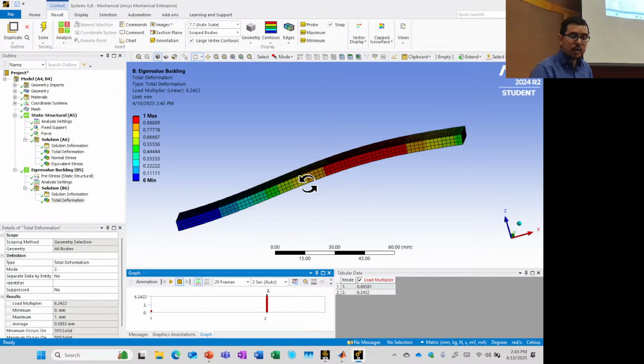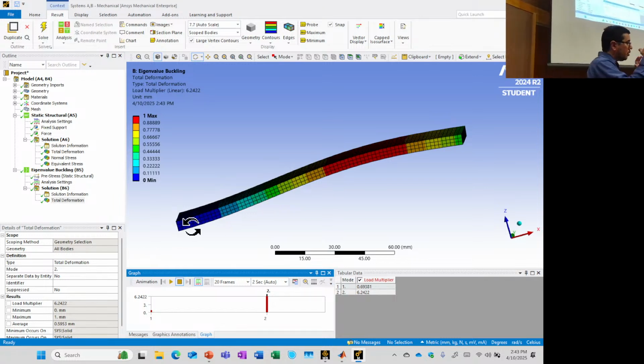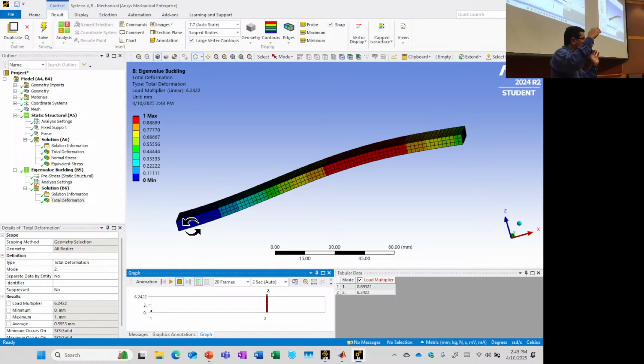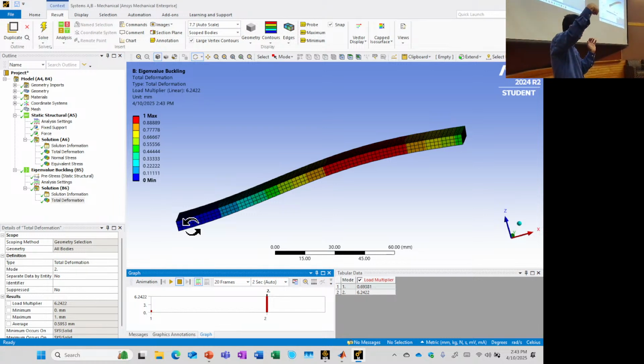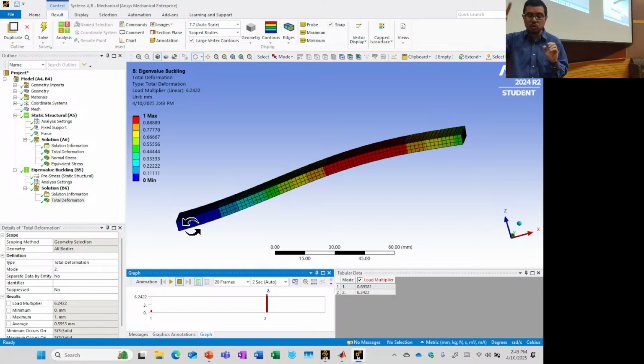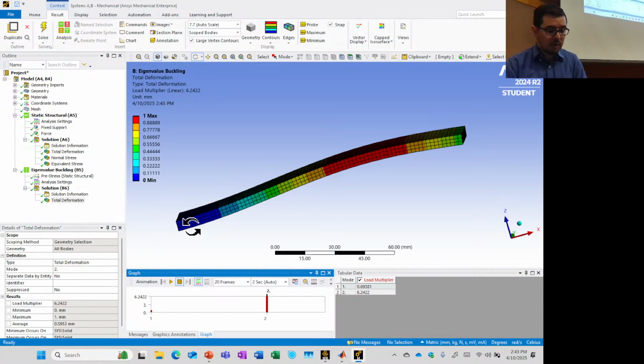You see, in this case it has to have zero slope coming out at the bottom because that's a fixed support. But the top has that force being applied, but it doesn't have to have that zero angle, and so this thing buckles out like that. All right. So this is mode 2, you could call it, if you like, and that's what it's called here.